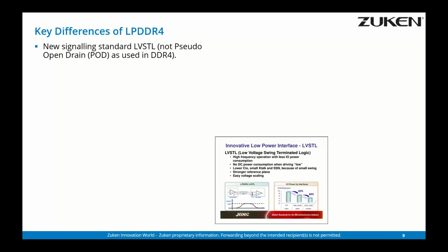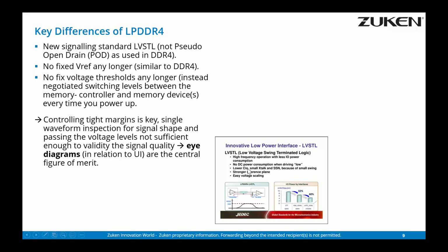One important thing to mention further is that contrary to DDR4, which has introduced pseudo-open drain technology for the signaling, we have now in low power DDR4 low voltage terminated logic, so low voltage swing terminated logic, LVSTL, having the advantages in the power management.